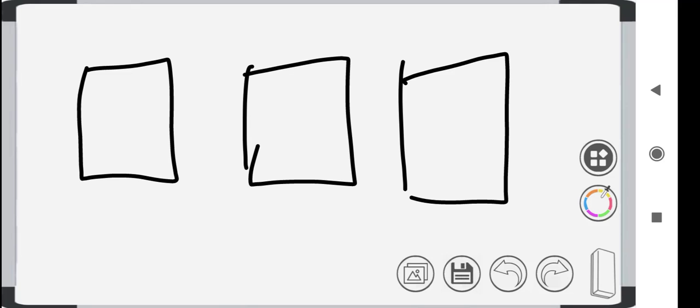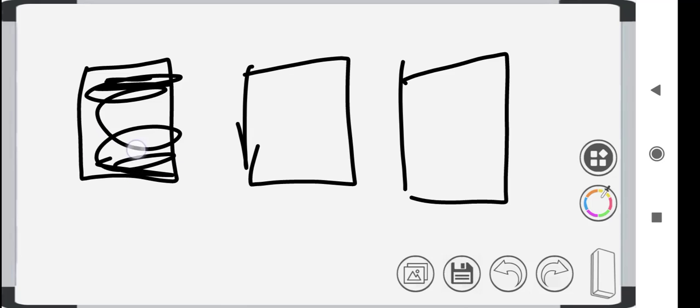They put a plastic cover over your document. Same here, these are the silicon steel stampings. The laminations are coated on one side by a thin layer of varnish, or they put a paper.